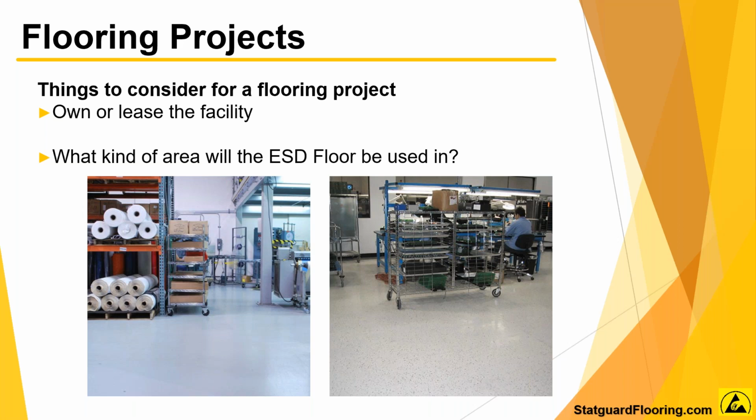Consider how the space will be used when making the decision on your ESD flooring solution. This should be given priority consideration when setting up a new, unpopulated EPA or facility. It is much easier and less expensive to do it up front than after the area is populated.